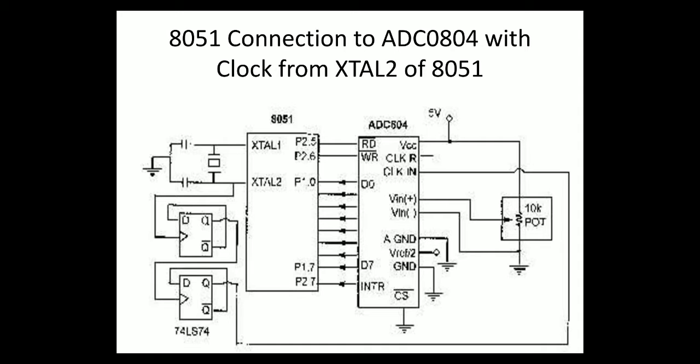So you can observe that the original crystal frequency of 8051 is divided by 4. Each latch will divide the frequency by 2, by half. When you connect the output Q of the first latch as an input to the next one, or it is connected as a clock to the next one, it obviously means that only when Q produces output does the next latch become operated.